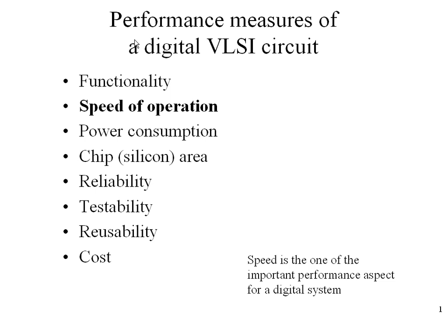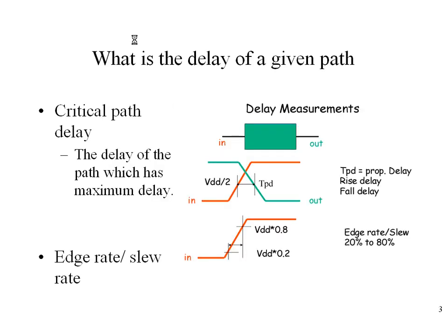If they are met, then what is the cushion you have, what's called slack time? Like, you ask for 5 nanosecond, is it giving 6 nanosecond, or sorry, you ask for 5 nanosecond, it's showing 4 or 3. That extra buffer, how much we have, all those things we are going to see now. Some of these topics I'm skipping, very simple topics like combinational delay.